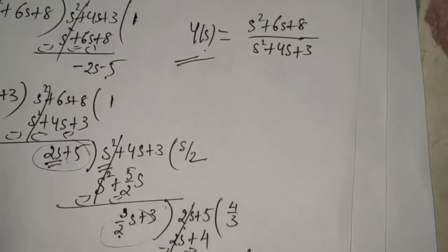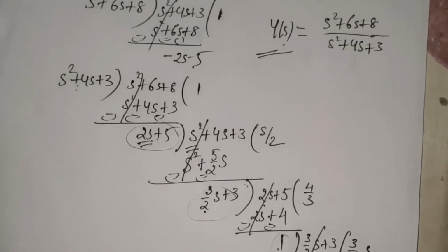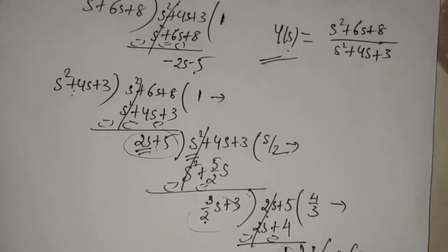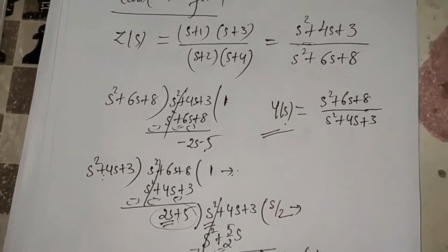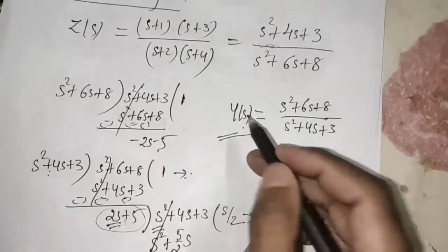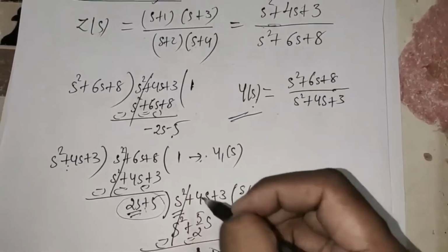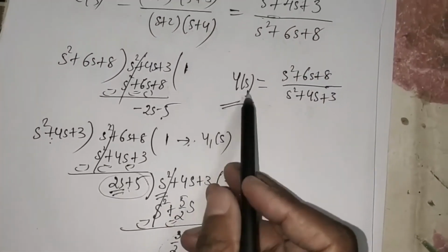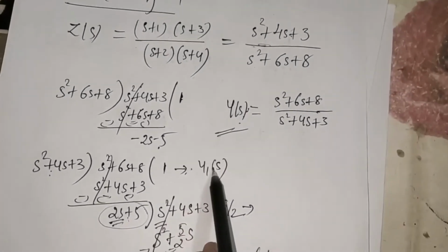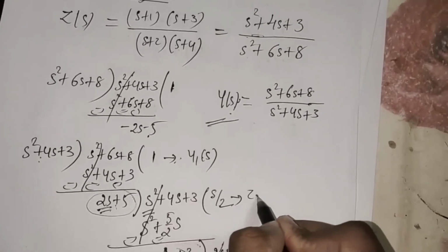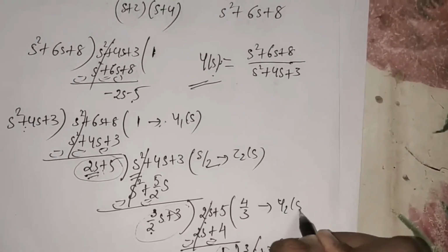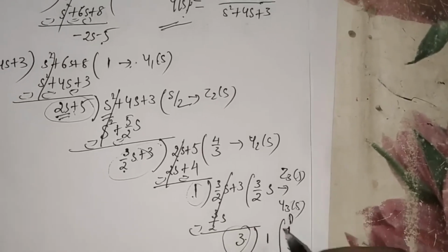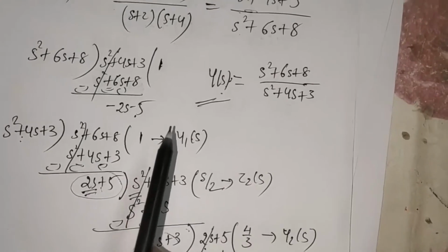So after we finish applying continued fraction, the quotients that we get, okay. So since we have done on admittance y of s, the first term is y1, and alternatively assign as impedance and admittance. So here, since we have considered y of s, the first term becomes admittance, the second one is impedance, third term is admittance, fourth term is again impedance, and the fifth term is again admittance. So it is nothing but an alternation of impedance and admittance.